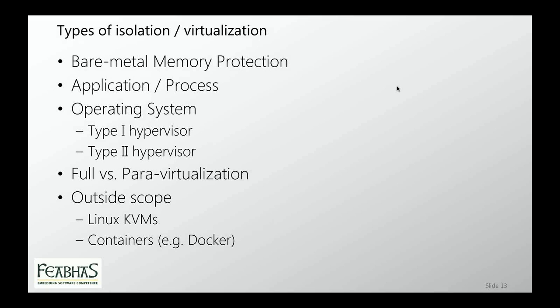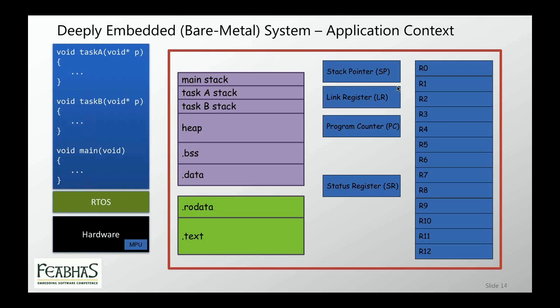So the first case is, if you take a modern microprocessor, say a Cortex-M processor today, where we're using a real-time operating system, then we do have our first level of support, and that's typically through things like a memory protection unit. Certain Cortex-M parts support a memory protection unit, and that gives us our first level of isolation. It means we can protect certain regions of memory, particularly regions of the RAM area. So, for example, when one of our tasks is running, we can ensure that it can't access the other tasks or the main stacks. We can control heap overflow and heap usage.